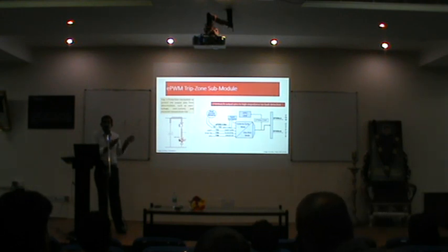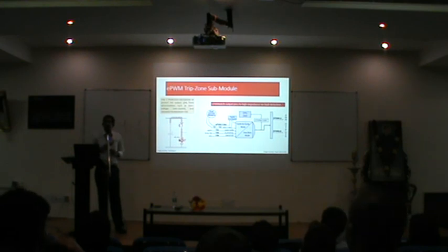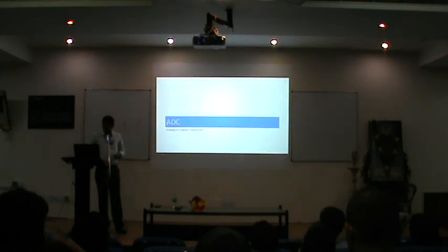Now these trip modules have different functionalities. Whenever it senses a fault, immediately it isolates one part of the circuit from the other. The PWM logic isolates the load from the source. You have a converter in between. That converter switching signal is made as high impedance state, which means that it is as good as the converter getting shut down. Converter is shut down, so obviously load source is isolated, trip mechanism. So that feature is required, that is also here.